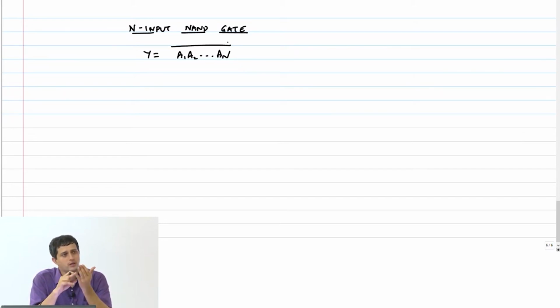First, draw the circuit, get the sizes right, then evaluate the delays. And only propagation delay, okay?